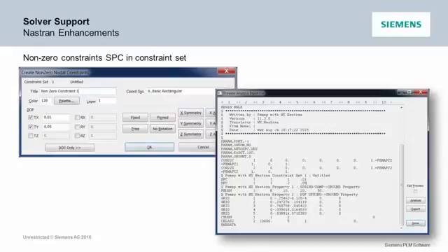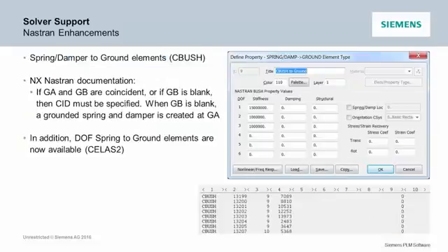For years, we followed the Nastran convention. If you want to do enforced displacements, you created it as a load, and then you had to go into the constraint set and actually constrain the same degree of freedom, because that's just the way Nastran worked. But we also now support creating non-zero constraints as SPCs. So now you just need a constraint set, you can put the numbers on, and you can have enforced displacements on your model without having a load set. And again, read-write: if someone sends you an existing model that already had this in it, we read it in and support it now.